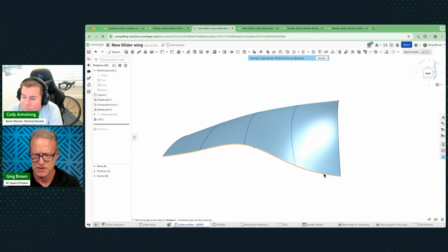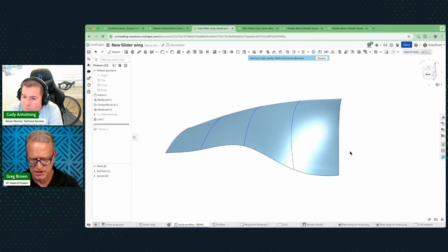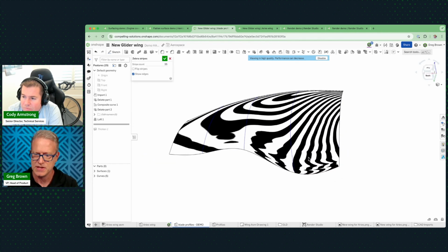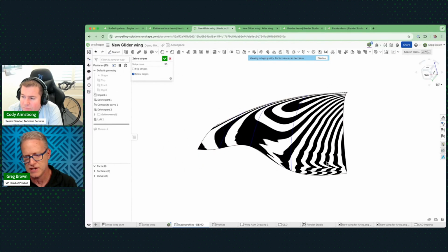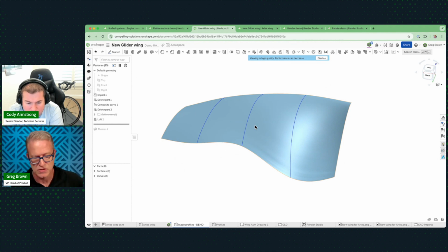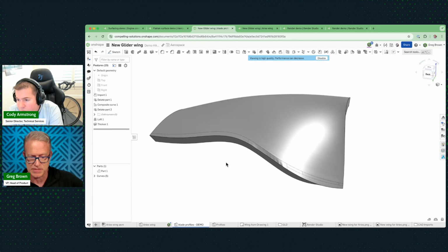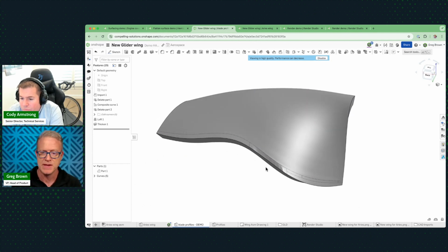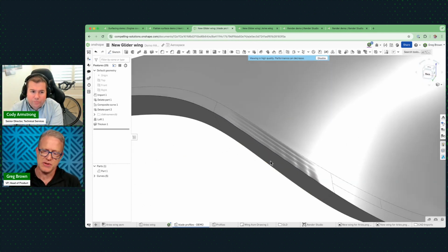So I'm going to invoke a couple of controls, and I'm going to do that using a zebra look here. So you can see here some significant problems down here in this loft. Now, if you use this to do downstream operations such as splitting or booleans or even thickening, you'll see that some bad things start to happen. So this is definitely a case of you should measure twice and cut once. You should make sure that your surfaces are good before you do things like thickening them or boolean or other operations downstream. Right, so that one's very obvious, but it's not always so obvious.